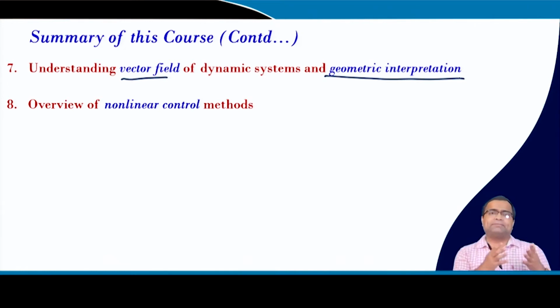That means, if the operating point or the equilibrium point changes, or the average quantity changes, then your transfer function parameters also change, and such transfer functions represent a linear parameter varying system, where either the transfer function or state space model, whatever you say, has operating point dependent parameters.